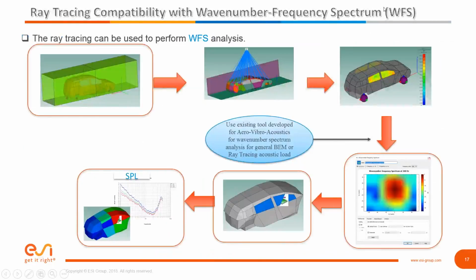for design. And to wrap up showing you how this is chained, again, you can use boundary element. You can do exterior models, for example, working with a pure SEA model, an exterior ray tracing model, capture how the exterior sound propagates. This example showing tire noise, how you get the greenhouse panel acoustic response on the glasses on the other surfaces. And then we can take advantage of some capability we introduced for wind noise and aerovibroacoustics. We can do a wave number frequency spectrum analysis, convert these surface pressures into acoustic loading, and apply those directly to your SEA model with the general surface pressure, get the resonant, non-resonant paths. This is really big. We've always had the ability to use boundary element to get the greenhouse panel loads, but that conversion was always tricky.